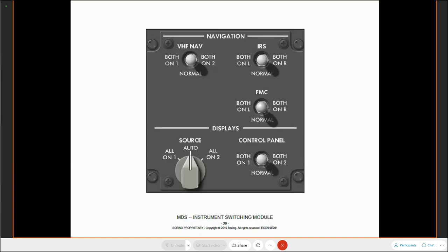The logic is done automatically by that fibre fabric card within the DPCs themselves. But if, let's say, a graphics generator or a graphics card should fail, then the displays will automatically reconfigure themselves to maintain 4 images on 4 displays. If I lose a complete display processor computer, regardless of which one, it doesn't matter, they're both the same. If I lose a DPC, then I've lost all the graphics cards and graphics generators within that DPC.